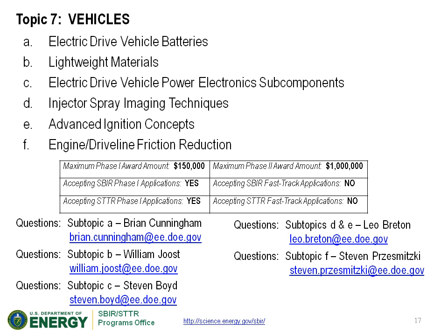Moving on to subtopic E, advanced engine concepts. Here we're focusing on lean burn combustion and gas engines. The concepts we're looking at include the extension of the lean ignition limit air and fuel ratio to greater than 20, doing this under high cylinder pressures up to 100 bar at the time of ignition, which would enable us to do higher load operation. And then we're also looking at lowering or maintaining ignitability, specifically a coefficient of variance of less than 3%.